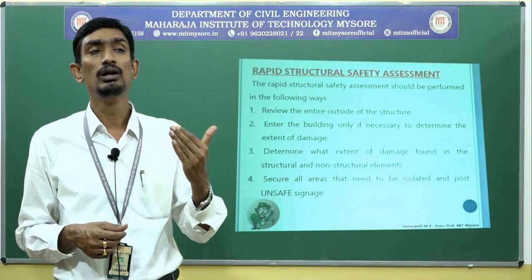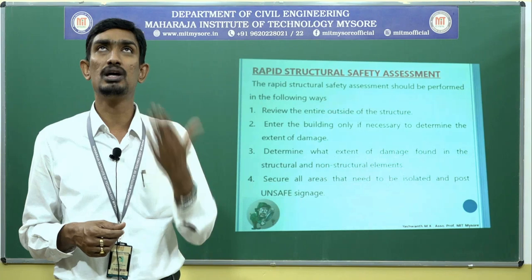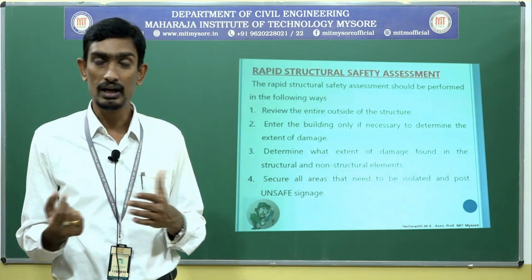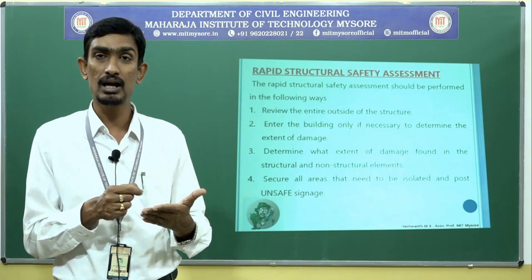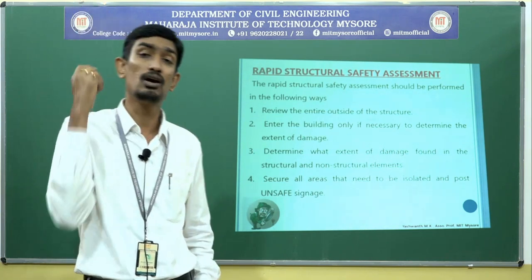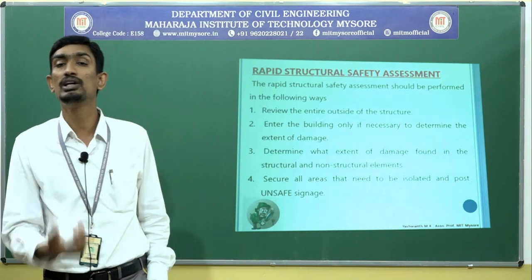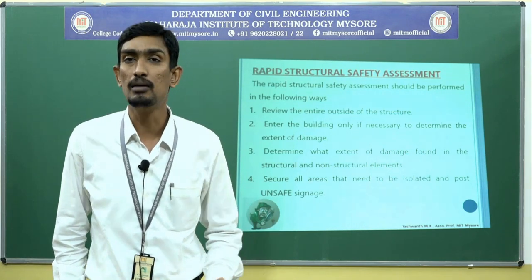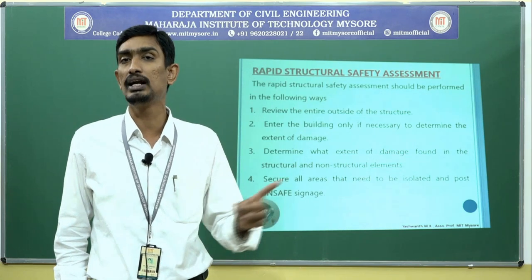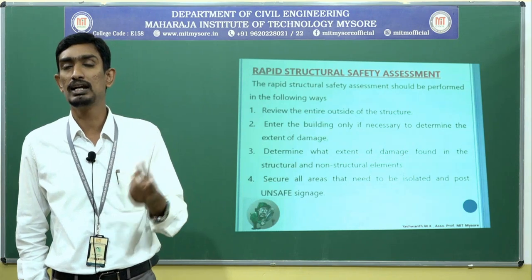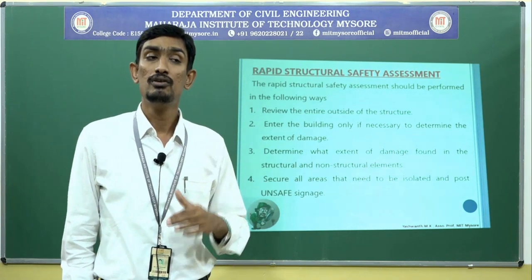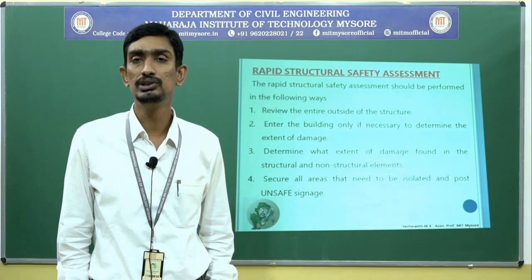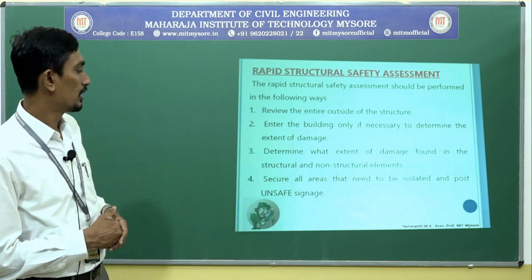Sometimes you can know physically by observing. Sometimes you need to take a photograph, come to the office and diagnose properly why it has happened. Sometimes you are also going to take out a chunk of concrete. All those things I am going to discuss; those are the techniques I am going to use. Because you cannot immediately come to the conclusion that it is unsafe or safe. That is what I highlighted in the purpose. It is very, very important as a structural engineer, as a design engineer, to do a lot of assessment before coming to a conclusion. Is it clear? Okay, next.